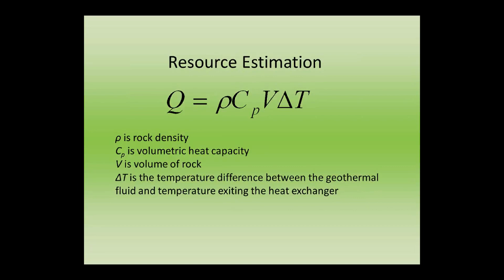A lot of this information is going into the well headers on almost all the wells. So rock density, volumetric heat capacity, you want to know the volume of the rock, and you want to know the temperature of the formation and the temperature to which you can drop it. This gets to be important when you decide how you're going to use it, if you're going to generate electrical power or something like that. And that's going to be a function of the heat exchanger.